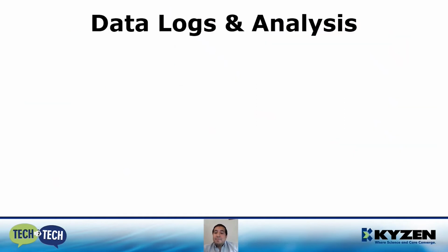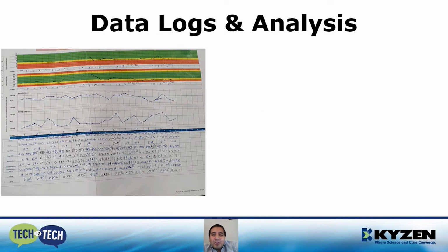We recommend that you keep a daily record of how the concentration measurement is behaving. This will help you identify trends like increasing or decreasing of the concentration along the days. Depending on the trends you observe, you will have to adjust the dial of the controller accordingly. You would have to measure the concentration, analyze, then react. And these data logs will be important for you to take the right decision on time and avoid the process falling out of range. An important note is that the tank will always be full.